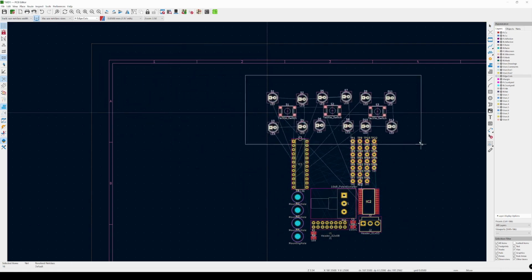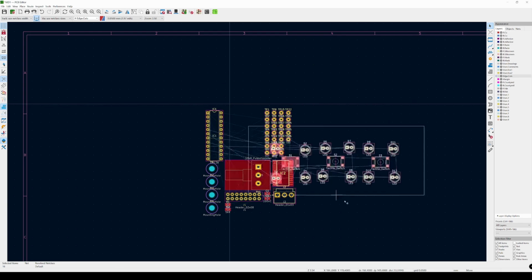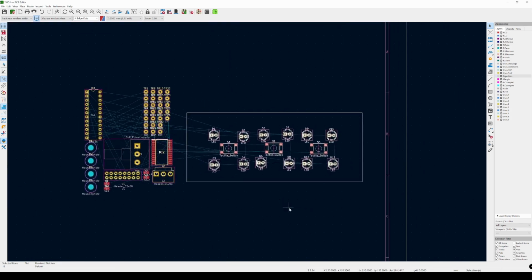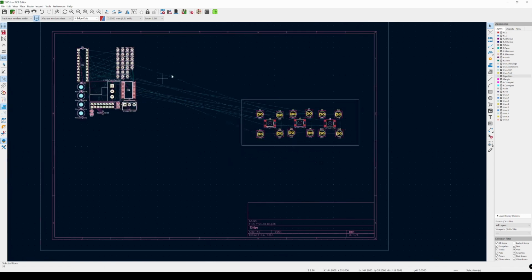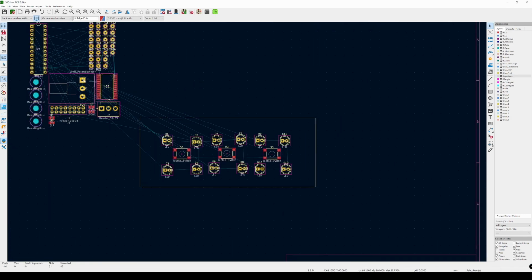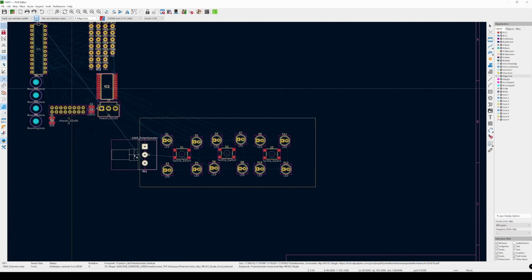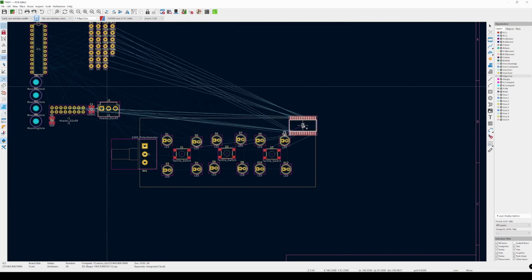Now, since I have now the key components in the correct places, or we can at least pretend that they are, I'm gonna bring the PCB into the center. Just something I like to do. Now, you just want to be placing components to wherever you find place. Again, click R to rotate to find more space.